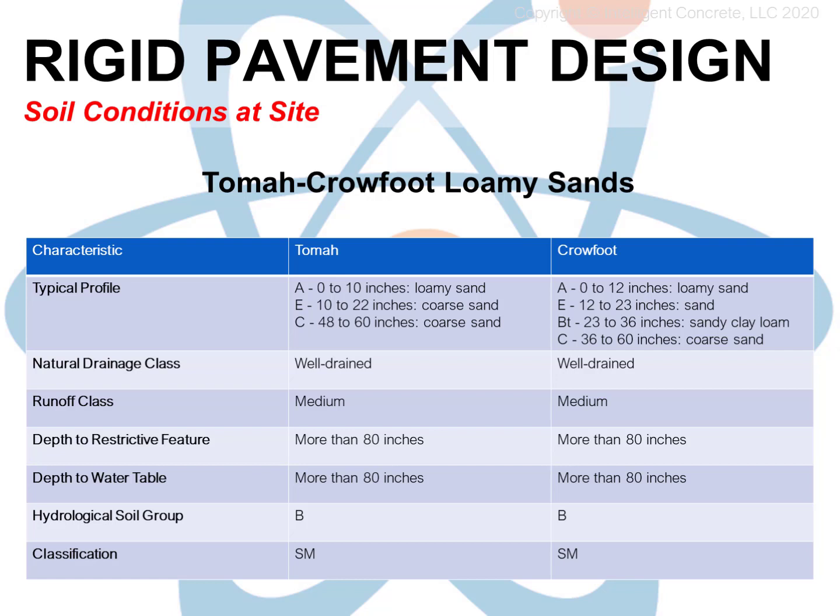There are other types of soil classification systems, each created to fill a certain niche. Farmers like the USDA and the USGS method of describing soils with terms like loams. Engineers like the Unified Soil Classification System with terms like silty sand. Highway engineers like to use a system developed by AASHTO, which is the American Association of State Highway and Transportation Officials. But that organization doesn't provide the online resources like the USDA and the USGS, so we won't use them today.